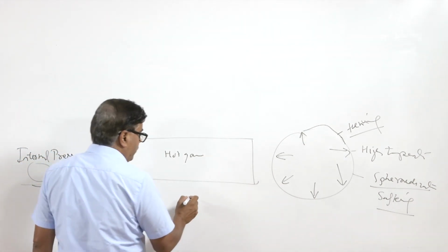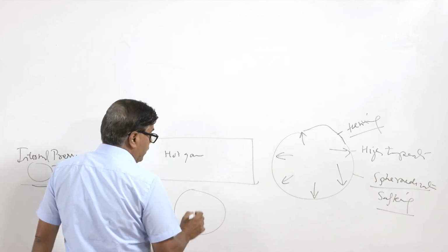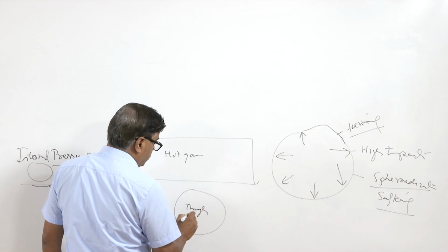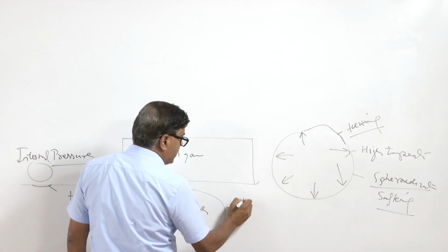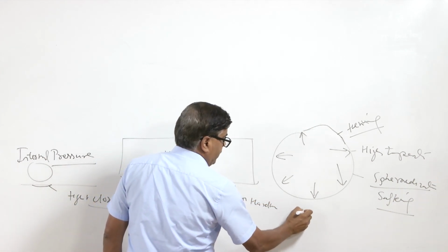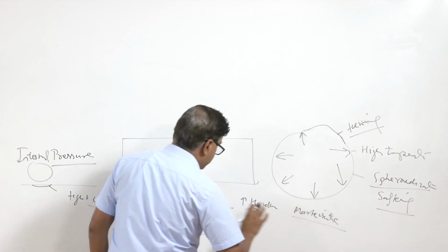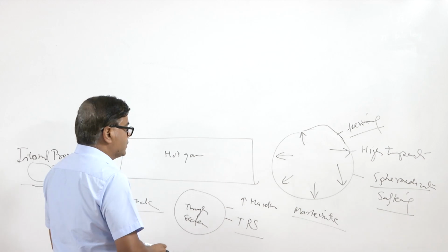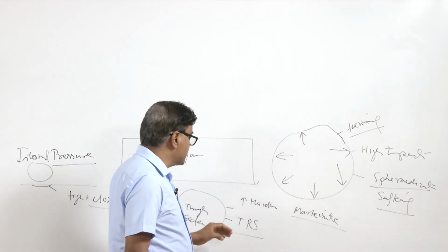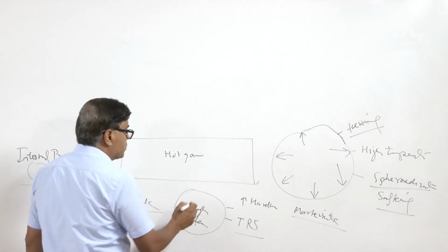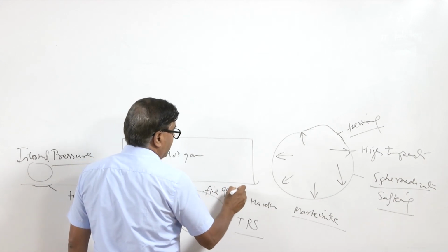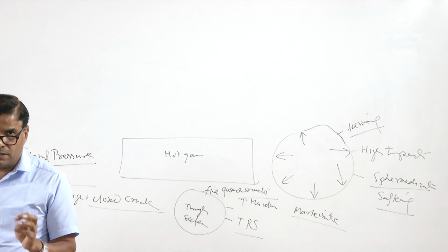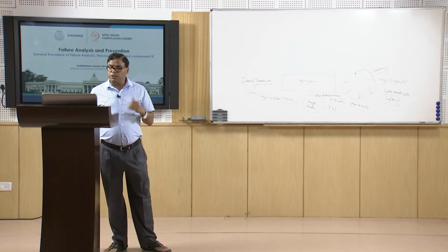Similarly, such cracks are also formed when the component is subjected to quenching, especially through-section hardening. This leads to an increase in the hardness of the steel, especially by martensitic transformation, and when martensite is formed, it is accompanied by the development of tensile residual stresses. The combination of increased hardness due to martensite and the presence of tensile stresses leads to the development of fine quench cracks. So, tight closed cracks indicate the possibility of fatigue fracture under cyclic loading, or quench cracks, or shot peening.